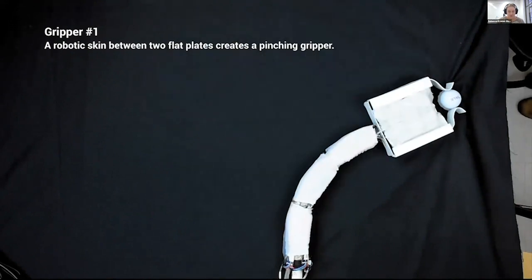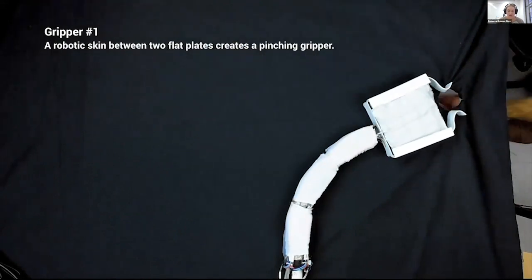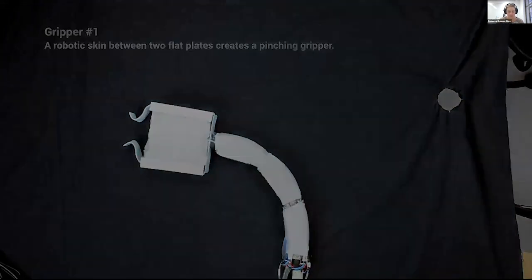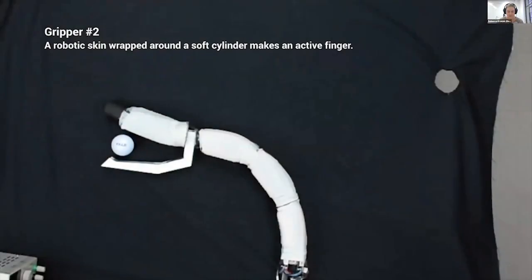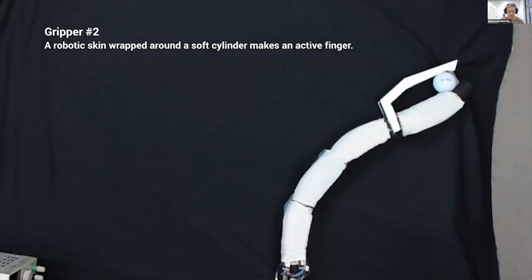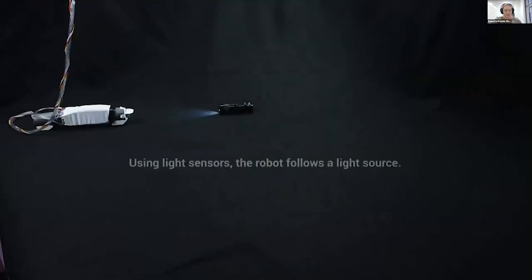So here we can use the 3-segment arm that you previously saw and now attach a gripper to make it a manipulator. So we made 2 types of grippers. The first that you just saw is 2 parallel plates with a robotic skin between them, and it just pinches together to grab that golf ball and move it to a desired location. And then we can remove the gripper and replace it with another type. Here, this is a gripper with a passive finger and an active finger performing the same task.